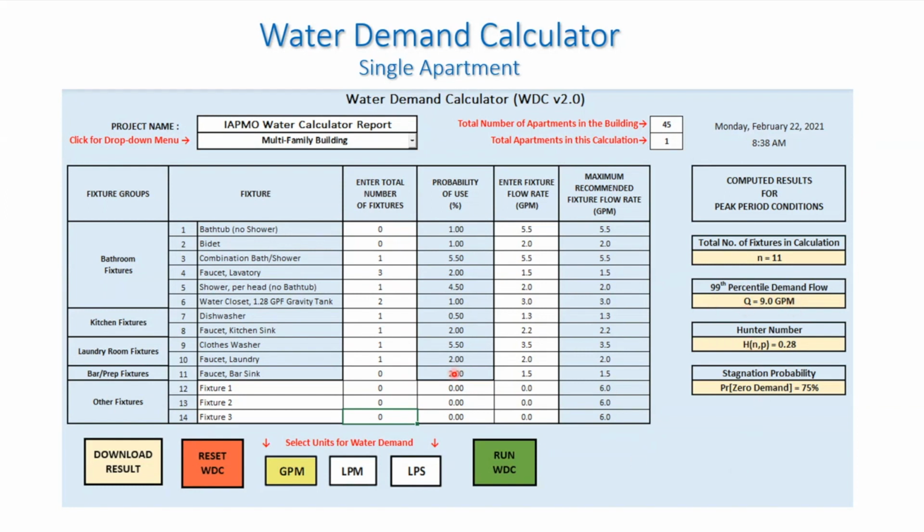So again, you're not using fixture unit values. You're only inputting the number of fixtures. You don't have a design curve. This will give you the peak design flow rate directly on the right-hand side. But this only estimates the peak demand. This doesn't tell you how to get from this point to calculate the actual pipe diameter required for any riser, branch, or incoming building supply.